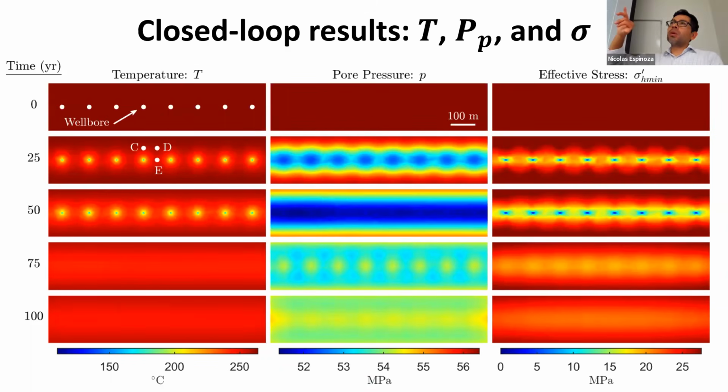What that's going to do is, imagine that you have a piece of rock in which the load on top remains constant, but you start decreasing the horizontal stress. What's going to happen in this case? If you keep this load constant, but you decrease the stress, you might fail your rock in shear, because this stress, vertical, is a lot larger than the horizontal.